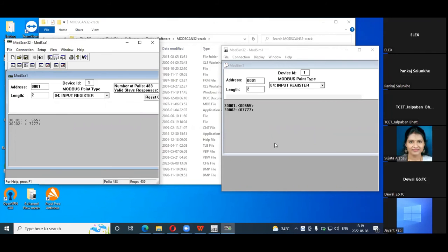It was first one, and that RTD is connected to one temperature transmitter. The function of the temperature transmitter is that it converts that change in resistance into the form of current. So as per industrial standard, we are using 4 to 20 milliamps or 0 to 20 milliamps.